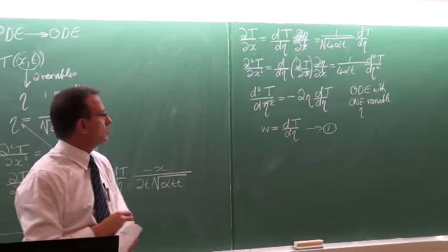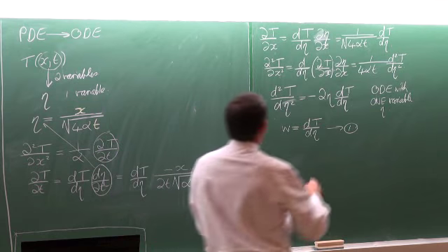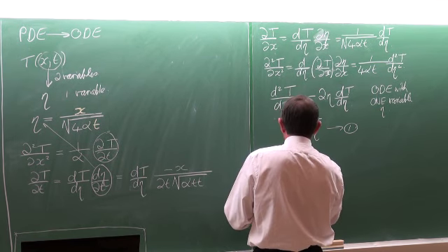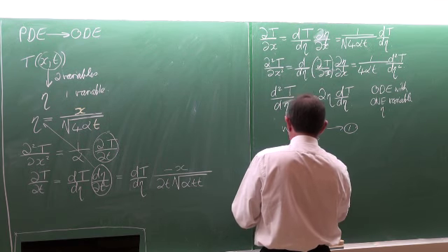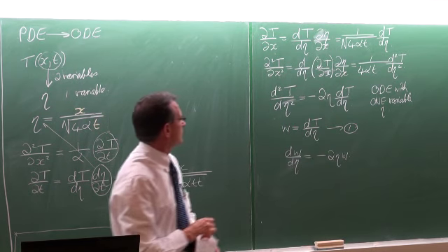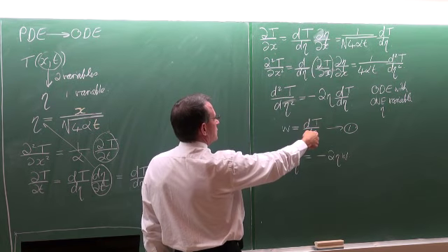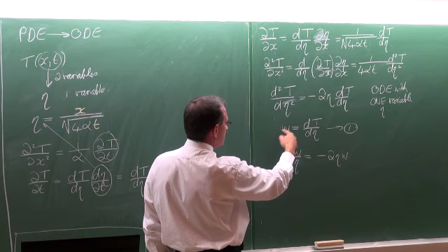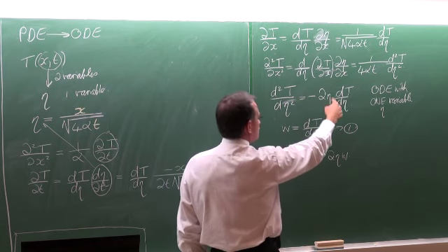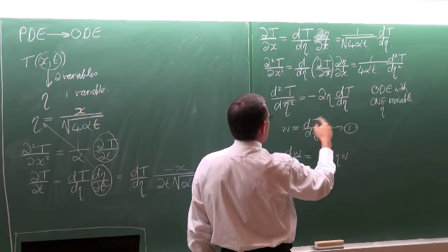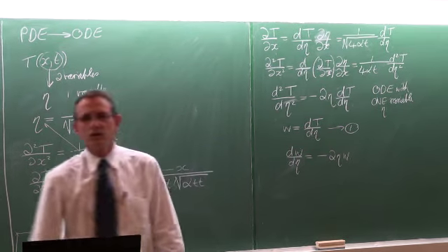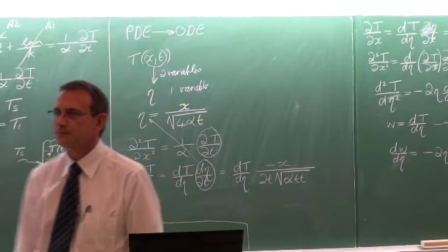We just define W, and now we can make it a first order differential equation by saying that dW/dη is equal to minus 2 times η multiplied by W. Okay. So if we say dW/dη, then we've got that term is equal to minus 2 times η, and dT/dη, that term is equal to W. So now we've got a first order differential equation.